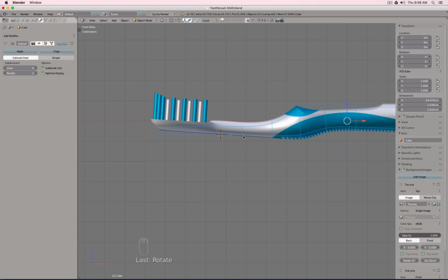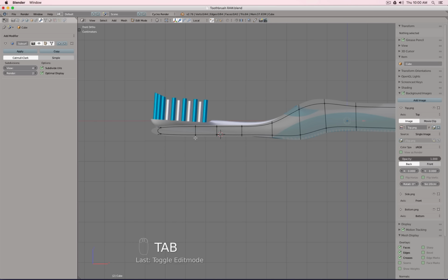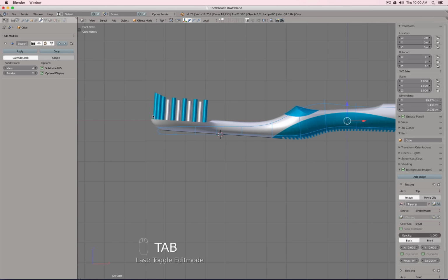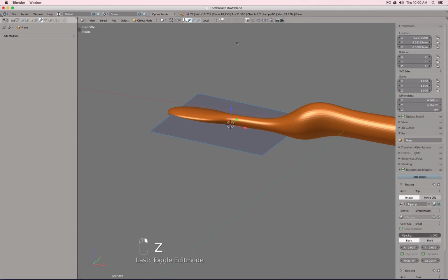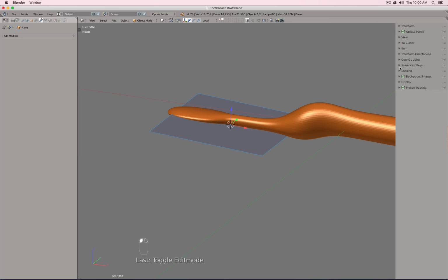Because essentially what I want to maintain is that all these CVs are nicely vertical and horizontal, but then the piece is actually bent. So I could select this plane, go to local, and then go to transform orientations. You see local is selected, and click plus.